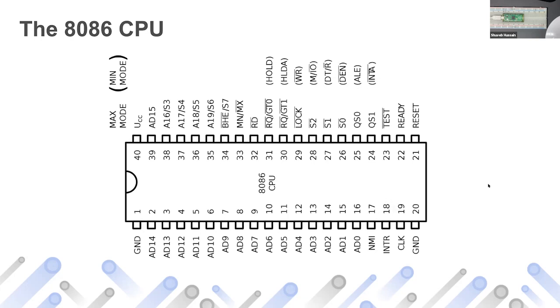And then every hardware device needs to interrupt the CPU. For example, a hard disk and Ethernet card and a keyboard and mouse and all of that, right? So what happens is that there's extra circuitry required. There's something called a programmable interrupt controller that will generally interrupt the CPU, right? And then the software needs to ask the programmable interrupt controller, hey chip, who really interrupted you? And then accordingly, the operating system figures out.